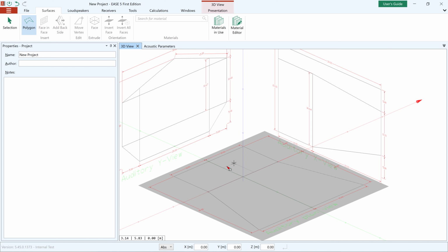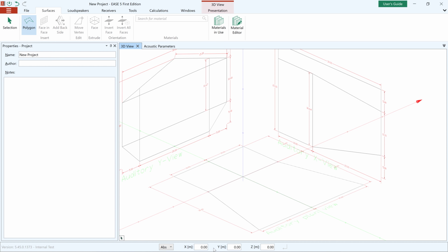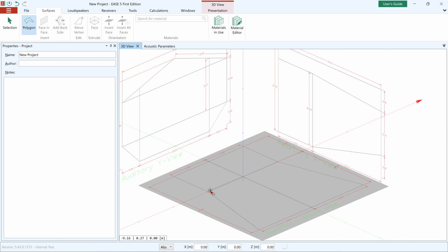We'll enter each of its vertices using the control bar you see at the bottom of the screen and absolute coordinates. You can see from the drawing that since my origin is here, this point is located at x equals -10. So just start typing -10 and you can see that focus switched to the control bar. And y in this case is indeed 0 and the same for z. So you can see a little cross with the preview of where the point will be inserted. If I switch focus back to the control bar just by pressing tab, for instance, see that the little cross is now at the position we want to insert the vertex indeed.